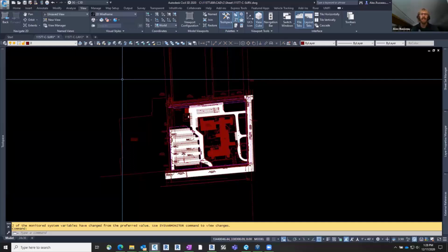Another thing that isn't great with Revit is the 20-mile radius. So if you linked in that file and there's something hanging out in space, you're going to get a lot of skewing of the visuals when you zoom in and zoom out. And oftentimes you'll know that's an issue when you first link in a CAD file. If it says the origin couldn't be found, it's going to link it center to center. That's bad news. Your file's going to be way off in space and you're going to have some issues in Revit. So always want to be careful with that.